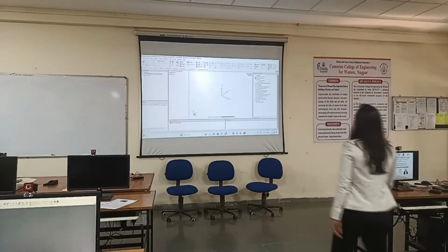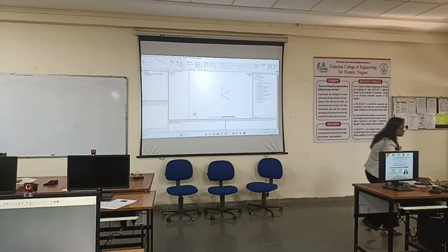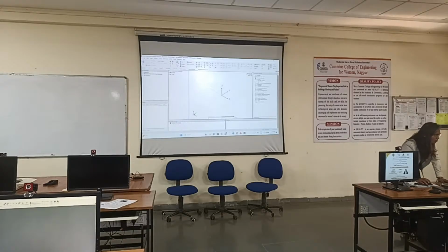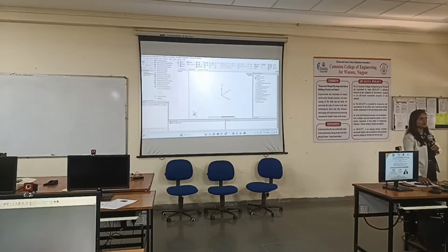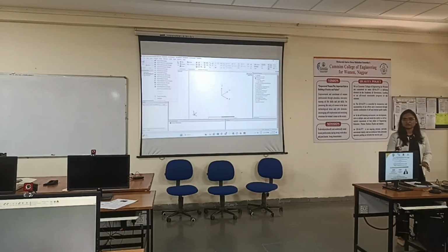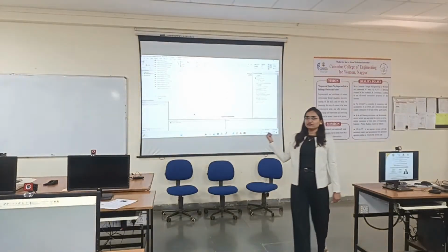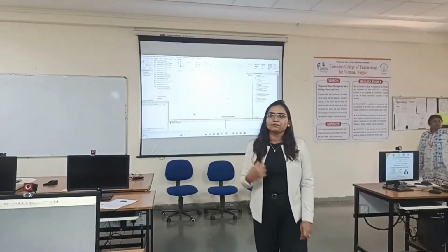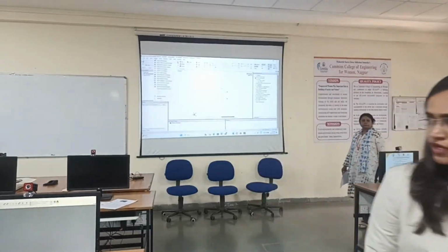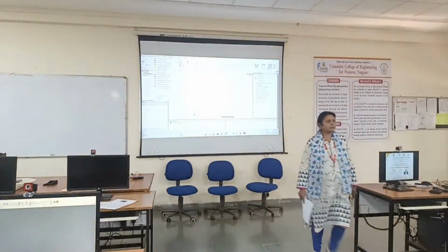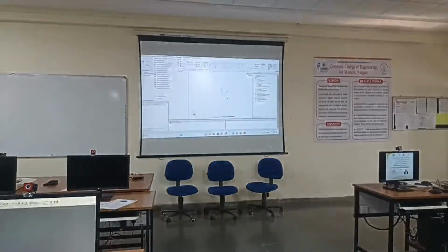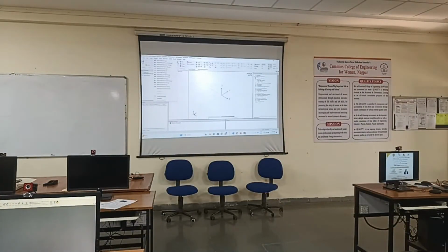The first step would be to go to Project. I hope you have already opened ANSYS Electronics Desktop. How to find this window, I'll guide you. Once you open this software, go to Project. In that, Insert HFSS Design will be one of the options. Insert.